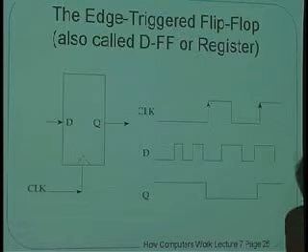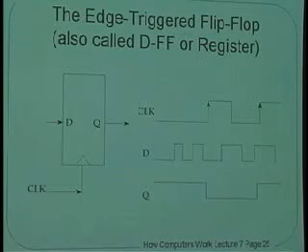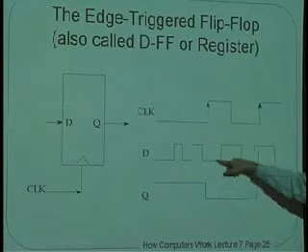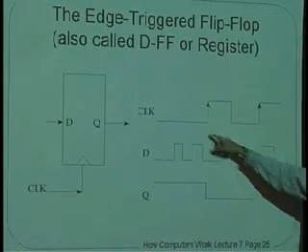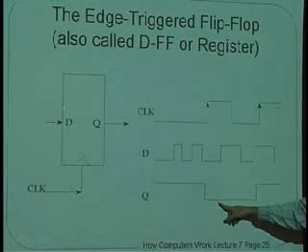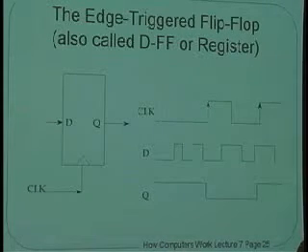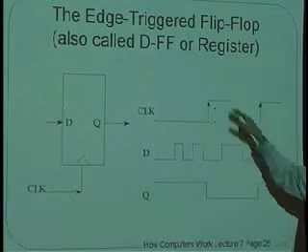Okay, let's do the final thing here, which is going to be, how do we build a flip-flop? Well, a flip-flop's a little different than a latch. Remember the latch, when the gate was high, it was transparent. D was transferred to Q as long as the gate was high. That's not true here. If the clock is high, D is not transferred to Q, nor when the clock is low is D transferred to Q. Rather, when the clock goes from low to high, D is sampled and transferred to Q. Now that seems like an incredibly hard thing to do. How could you take a picture of D kind of in an instant and not be transparent, not pass through D either when you're low or you're high?